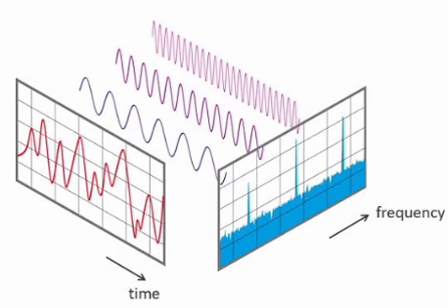Properties: no feedback is required. They are inherently stable, given the equation y[n] equals sigma i equals 0 to N b_i x[n − i]. They can be easily designed to be linear phase by making the coefficient sequence symmetric. They are computationally complex. Moving average filter: y[n] equals b₀ x[n] + b₁ x[n − 1] + b₂ x[n − 2].